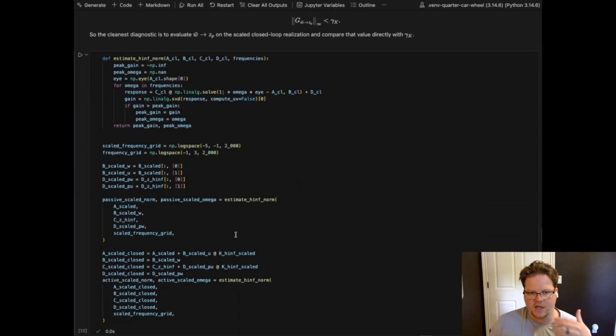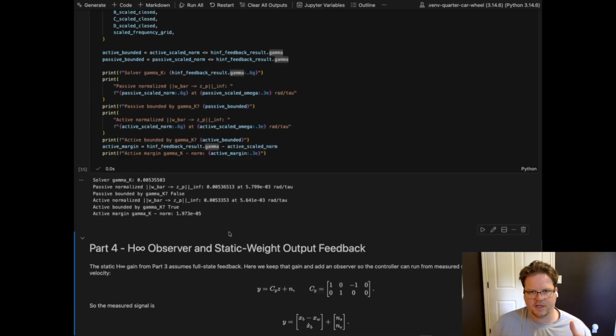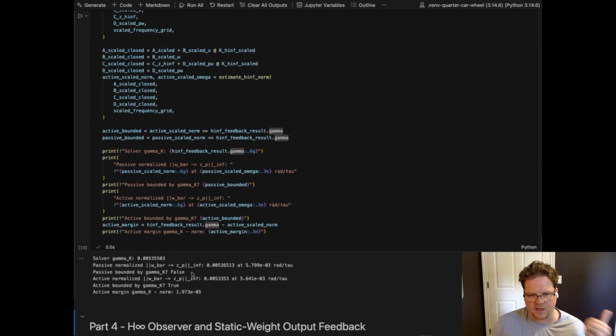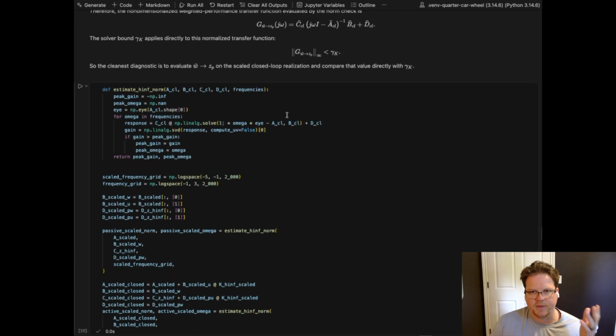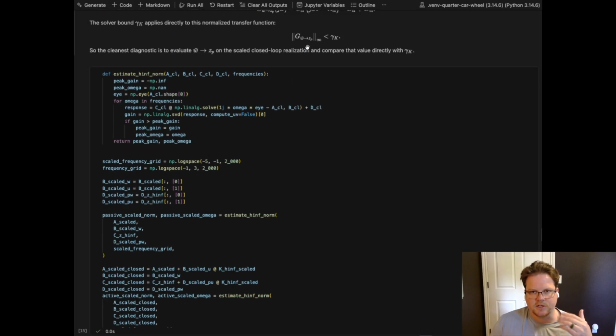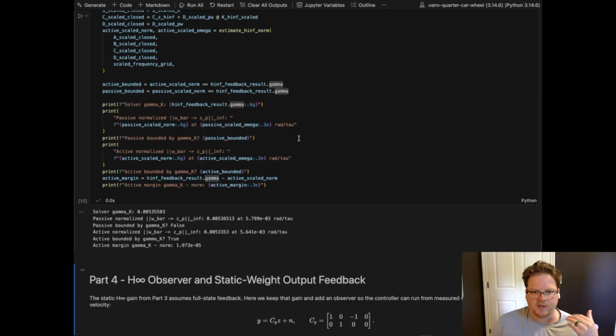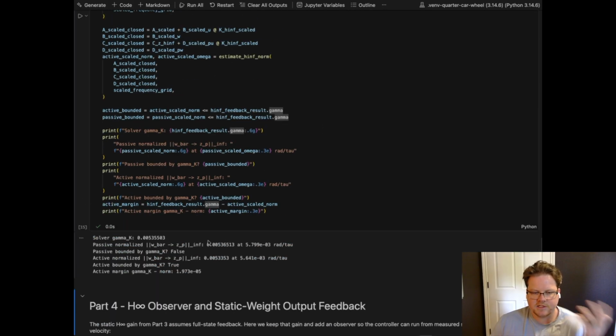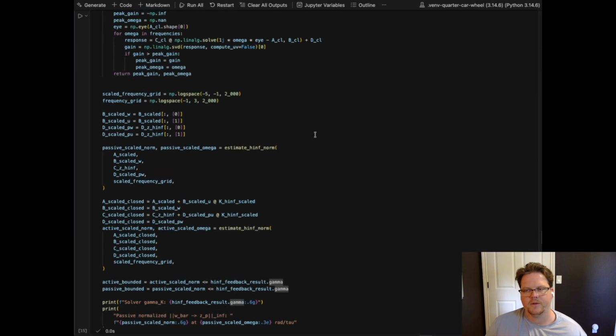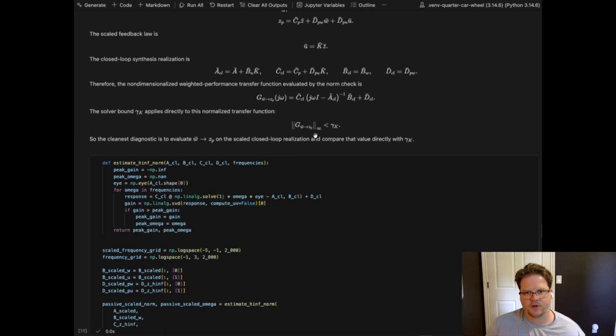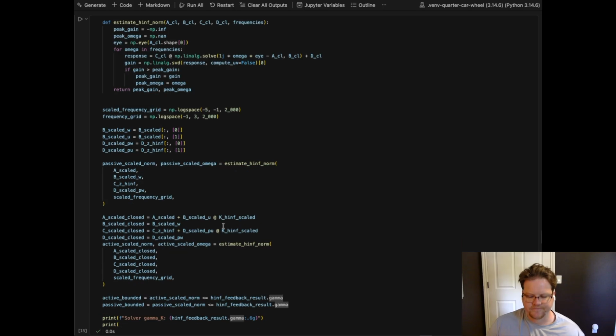And then as showed, it is in contrast to the passive system, which is not. And it's small, but it's in this non-dimensionalized space. So we can see that passive is not robust with the H infinity norm metric with that disturbance here, W to ZP, whereas the active control is. And that's exactly the goal here. We're trying to reject disturbances per the criterion that we've defined above.